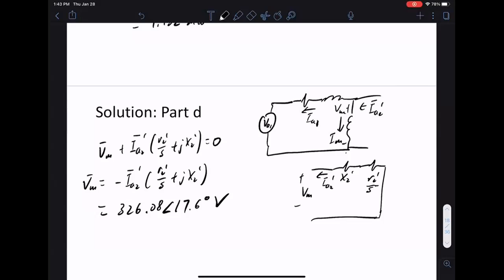Yeah, so pay attention to the question. If the question gives you XM, then you cannot ignore XM. Every question should be clear. We should have explicitly said, if XM is given, the question will explicitly say, take the shunt into account, something like that. But in general, if you're given XM, you need to use it. If you're not given XM, then don't worry about XM. If there's no XM, this calculation is much easier because you can directly use IA2 prime as a current. Here we have XM, so I have to look at how we have to divide the current.